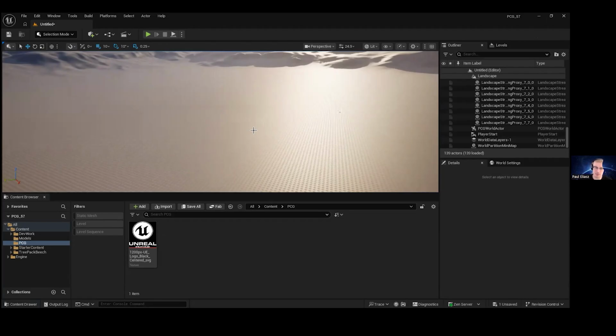Let's say you have a landscape. Well, there are a few ways to do this. For the first one, what I'm going to show you is the surface sampler, because there's also a spline sampler, a texture sampler, and a mesh sampler. We're going to have four different examples, which I'll try to fit within the 45 minutes. But for now, let me crack on so I can show you the most ideal and standard way of creating a very simple PCG.